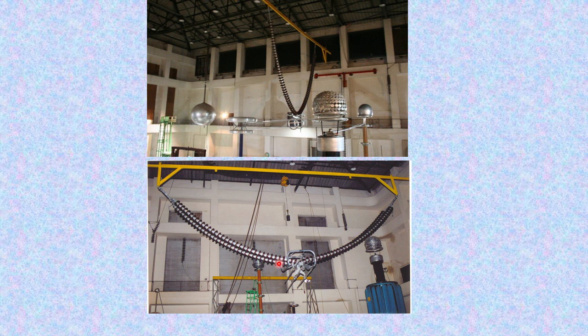Practically, making the entire string uniform is highly difficult, because it depends on the stray capacitances from the ground to the insulator string, from the tower to the insulators, and again the coupling between each of the insulators, where you have a capacitance. So, ideally making it equal is very difficult, highly impossible. So, proper grading is done with the help of corona control rings and arcing horns near the ground end. This will help to reduce the stress on the insulators, particularly those connected near the high voltage end.